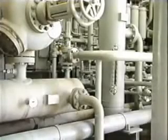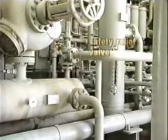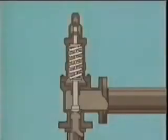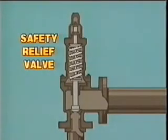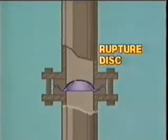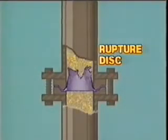Other safety features include rupture discs and safety relief valves, which are installed in the compressor lines to relieve excess pressure. If, for example, a discharge valve were to malfunction, causing a sudden increase in pressure, the safety relief valve would open to release the gas into a vent, or flare line. A rupture disc in the same situation would simply burst to reduce pressure.